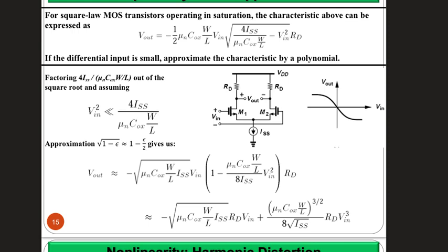The result of that is that you have an input-output relation that you see up there between the input of this circuit and the output of this circuit, which shows some linearity here, and then it starts being nonlinear, and then after it starts being nonlinear, it becomes kind of saturating. This saturation causes an effect in amplifiers that we call compression, right?